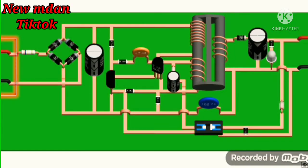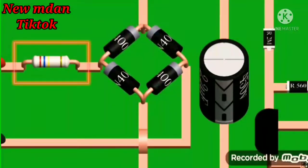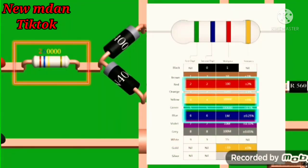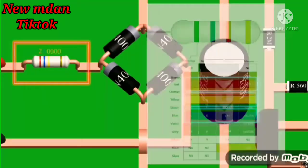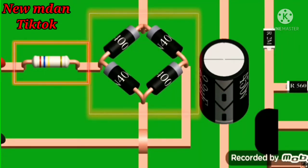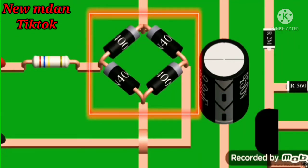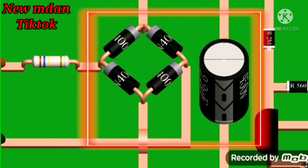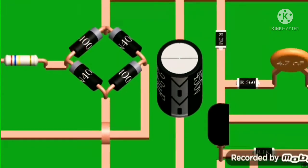This red wire is the phase wire and the black is neutral. First, we have a resistor. By observing the color bands and reference table, we can see it's 260 kiloohms. This is a fusible resistor which prevents damage from overloading. Then there is a bridge rectifier made by 4 of 1N4007 diodes and a filter capacitor of 450 volts and 2.2 microfarad. This circuit converts AC to DC.